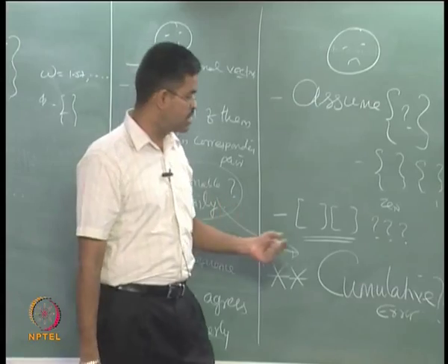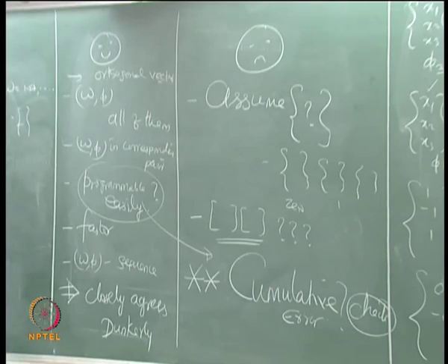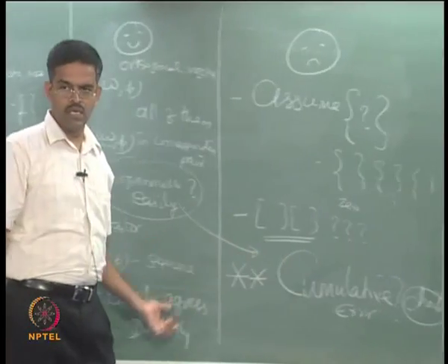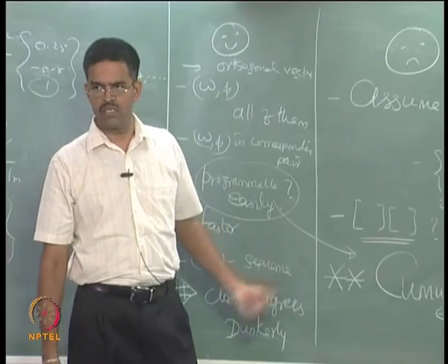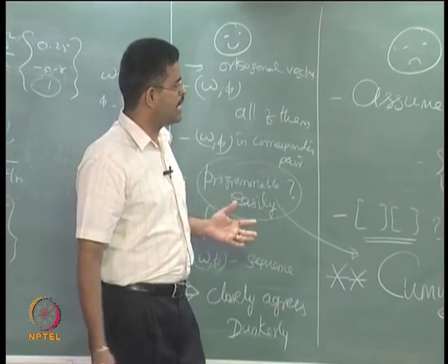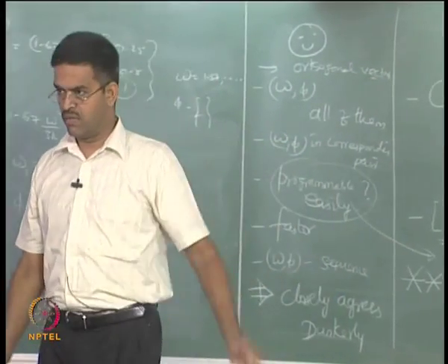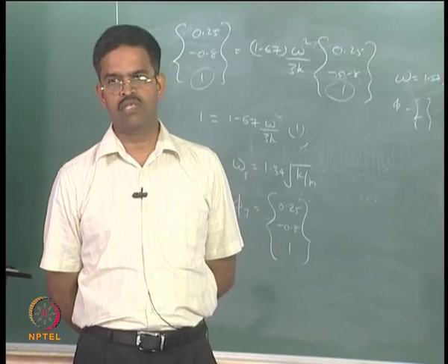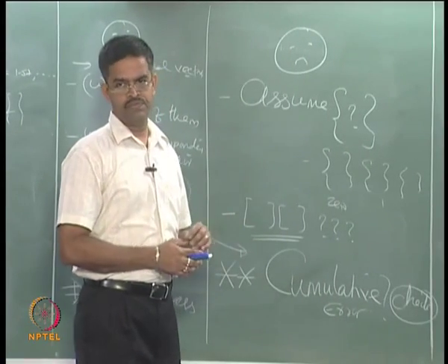The checking process is to check this with Dunkerley. That is how the method was developed. But this method will not check the eigenvector or the mode shape, it will check only the eigenvalue or the frequency. So, check this with the frequency and also physically see the first mode should be all positive values or all negative values, whatever may be. So, there should be no zero crossing. I mean that physical understanding you must have. If you have these two physical understandings, this method can be easily handled.